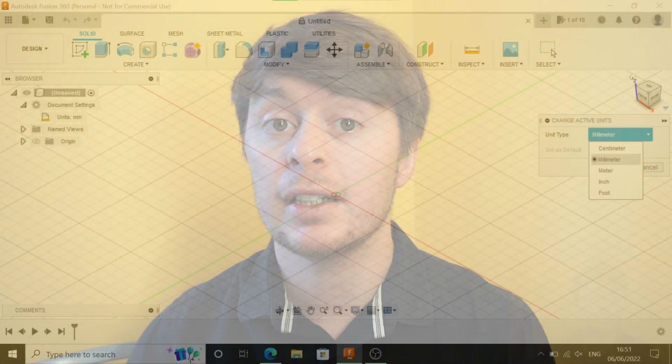I found a .step file is a lot better than some of the other formats, such as STL, for creating a mesh, as it seems to simplify the structure which a mesh is generated from, whereas an STL can sometimes have a few quirks, shall we say, when you're converting it to a mesh for FEniCS.